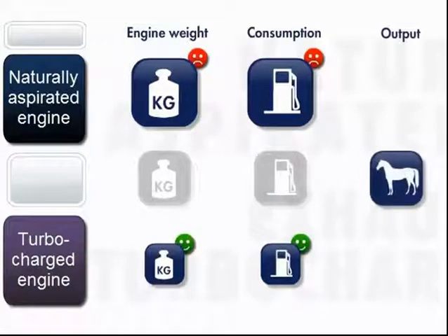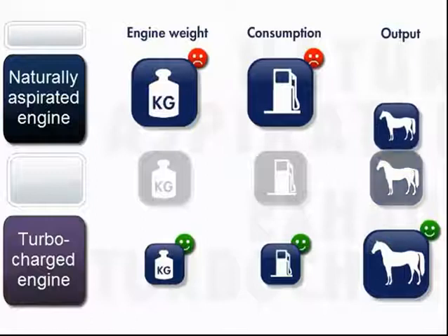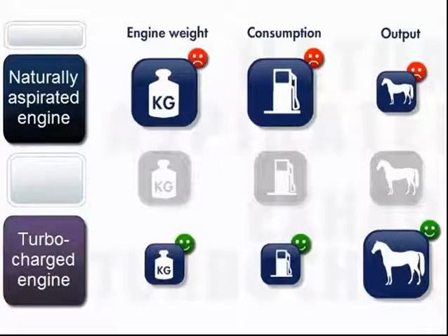Output. Exhaust gas turbocharging allows an increase to maximum torque and maximum output, since the mixture throughput per working cycle is increased by charging. This increase allows either the use of a higher output engine with virtually the same dimensions as a corresponding naturally aspirated engine, or allows what is called downsizing the engine, i.e., achieving a comparable output from a smaller and more lightweight machine.